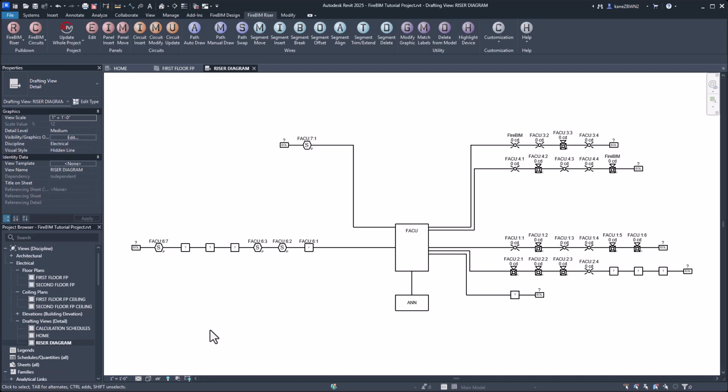You'll see that some of these don't have actual fire alarm device graphics. They just have a square with a question mark. That is the placeholder graphic that we use for devices that have not been configured to show a different graphic. That is a default that is specified in our project options. It is a thing that you can change if you so choose, if you want there to be a different default graphic that comes in for devices that aren't configured.